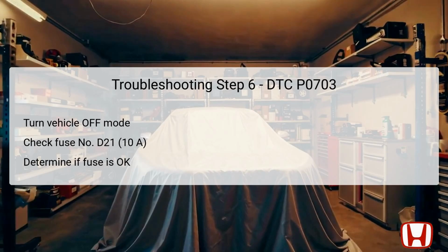Conversely, if the fuse is blown, replacing it is essential. Additionally, ensure to check for any shorts to the ground in the circuit for a complete diagnosis, as this could also explain the malfunction indicated by the DTC.